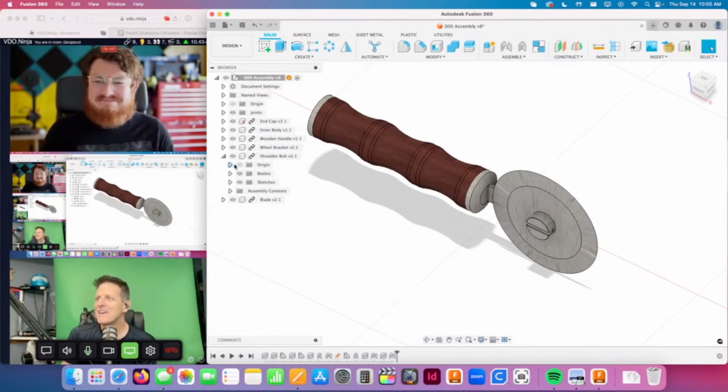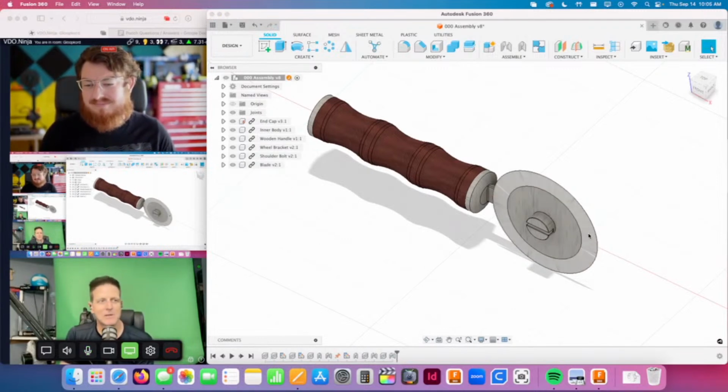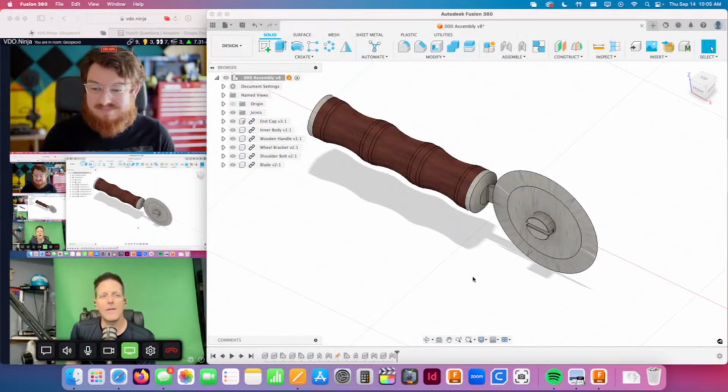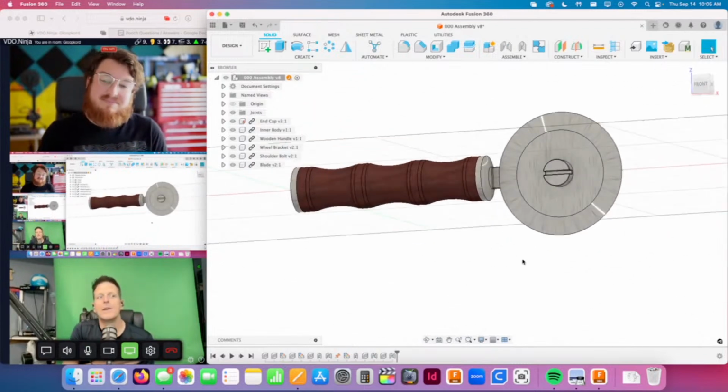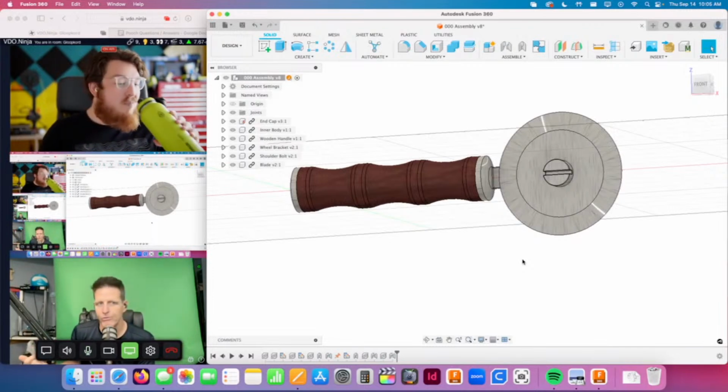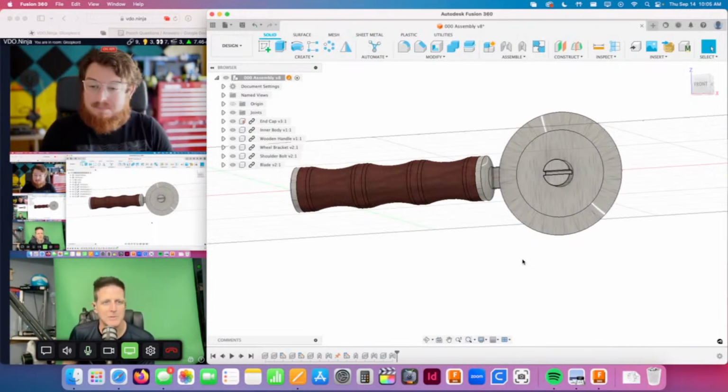So here's a good one, and maybe this is relatable to you guys, but oftentimes when I'm iterating on something, we're constantly putting holes in things, for various purposes. Especially when I'm 3D printing, no two printers are necessarily calibrated the same way. Holes come out plus or minus depending on the quality of the printer, the decisions it makes, and what slicer you're using.